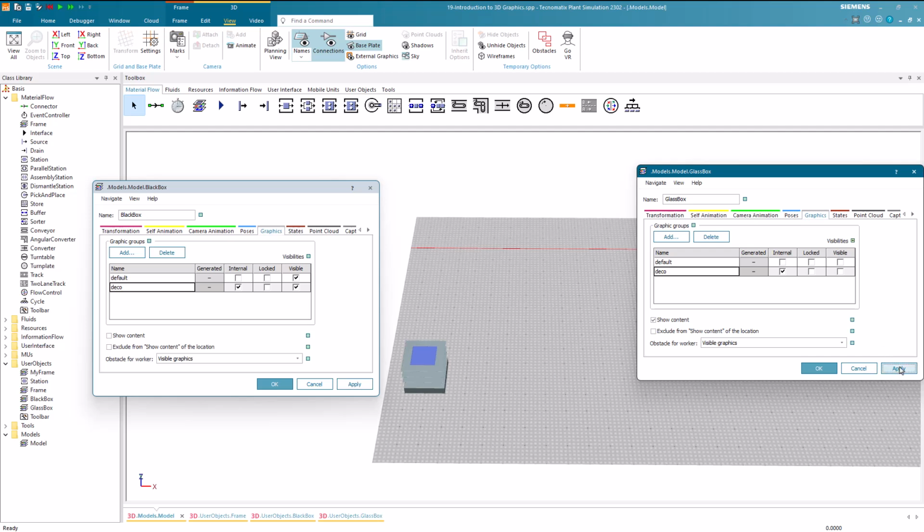Additionally, you might ask in which use cases black box frames are used. Let's assume that you have a production facility that consists of several areas, but you do not want to visualize all areas in the model frame. You could now take a cuboid of length 1 by 1 as an external representation for the areas that you do not want to visualize. Thus, a sub-area would be represented by this cuboid, which could be of arbitrary size. This could be used as a possibility to increase the performance for large productions, since one does not have to present all sub-areas.